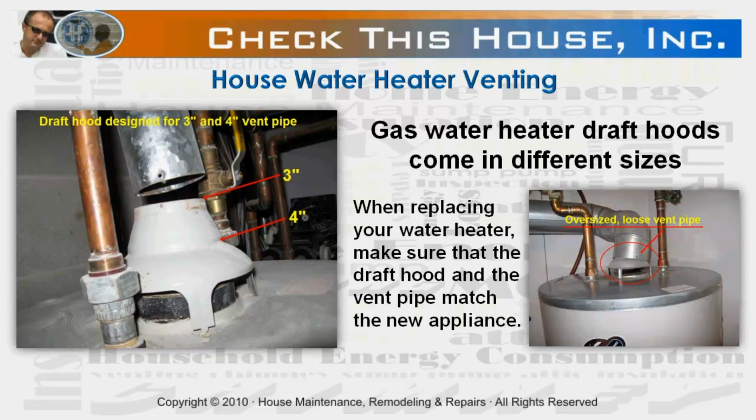Gas water heater draft hoods come in a few different sizes. It's always best to use the new draft hood that came with your water heater, not the existing one that was attached to the old appliance, even if the new and old one look absolutely the same.